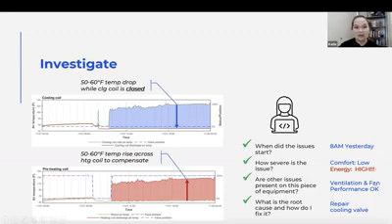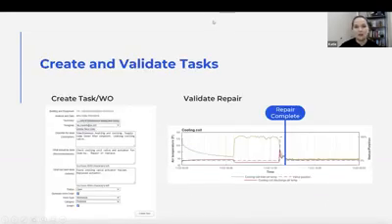And I looked at my air handler for any other kind of faults that are coming through. Ventilation is fine. My fan performance is fine. This is just the coil. And so I know my root cause. I need to repair that cooling coil. So I create a work order and I say, go fix that coil. I know exactly what it is.